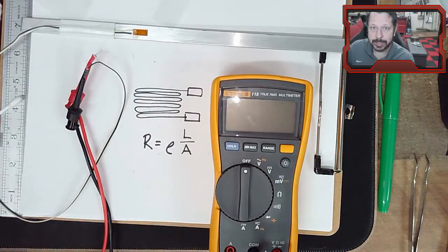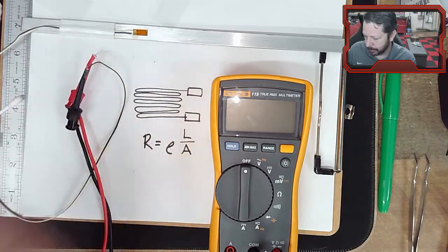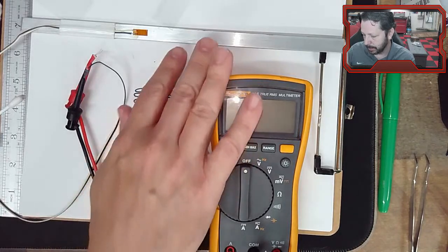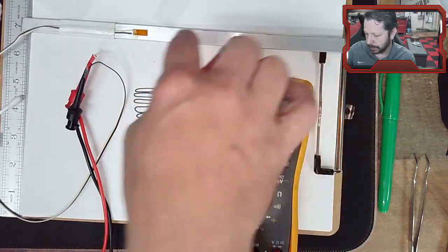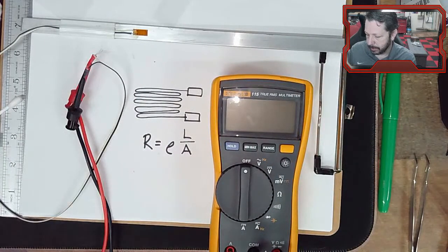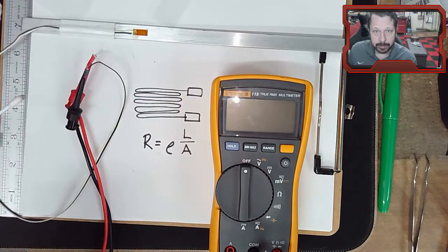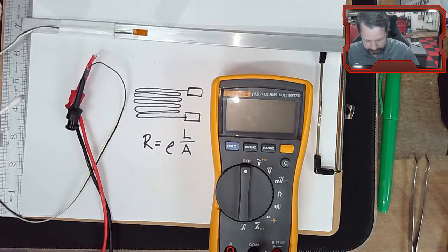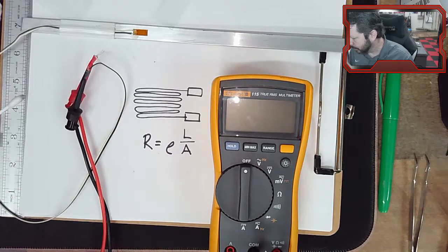And at that point, we can start to do the same type of stuff where we do an analog read and we have a value from 0 to 1023. We can interpret that and figure out what it means as far as this resistance change, and what that means as far as a strain and a force that causes that strain in our beam here. And we've created a little load cell at that point. I think that's enough for today. We actually have more time, but I think we covered all that I planned to cover.